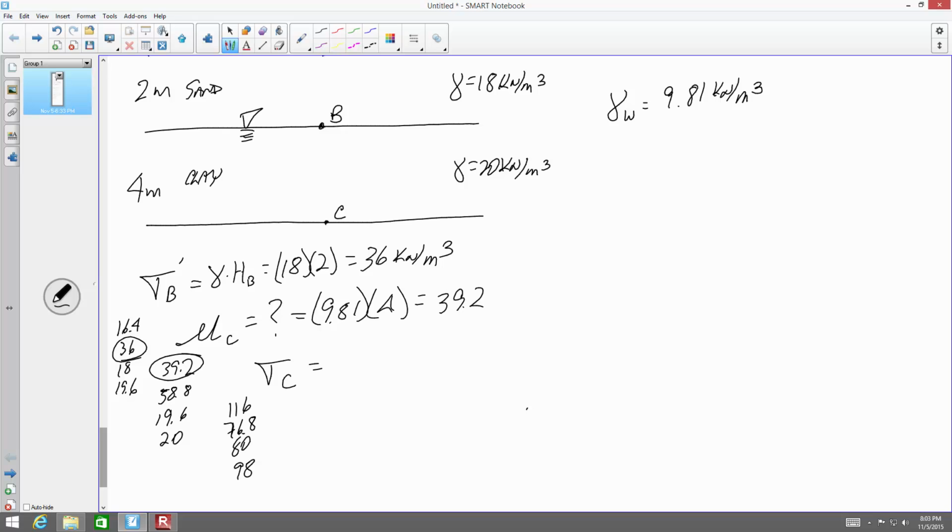What? Run that again. What math are you using to get there? Total stress at C, I'm going to say it's straight off. You got whole numbers for your unit weights, that'll end up giving you whole numbers, not decimal numbers. And you're going to subtract 39.2, which is your pore water pressure. That might work. How would you calculate it if you couldn't deduce that?